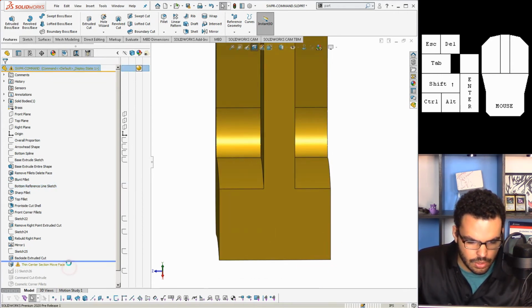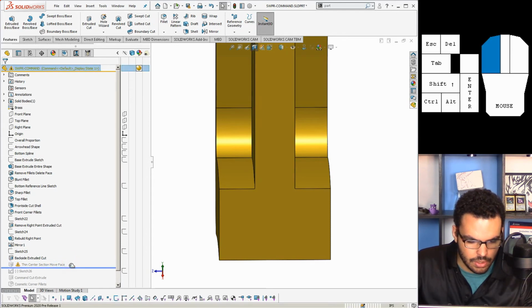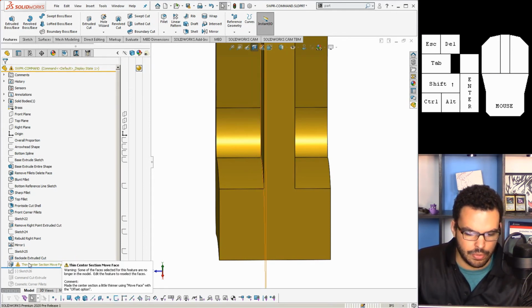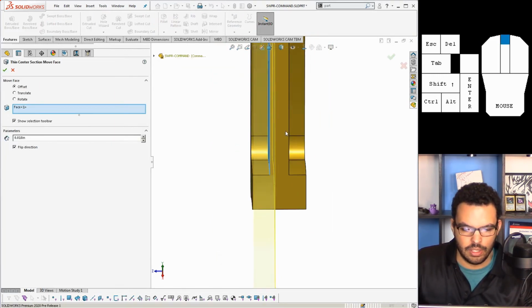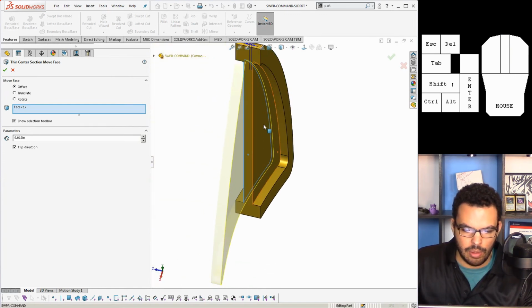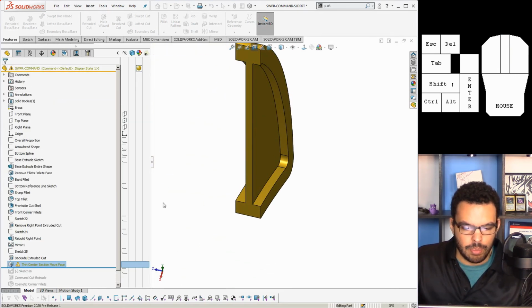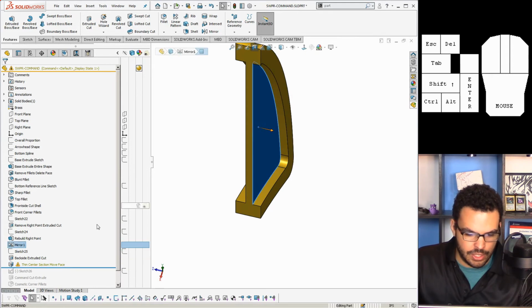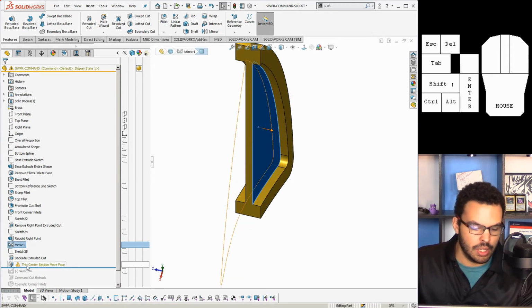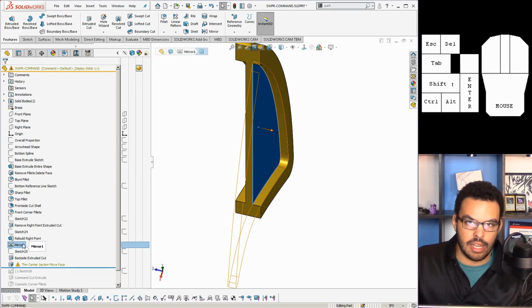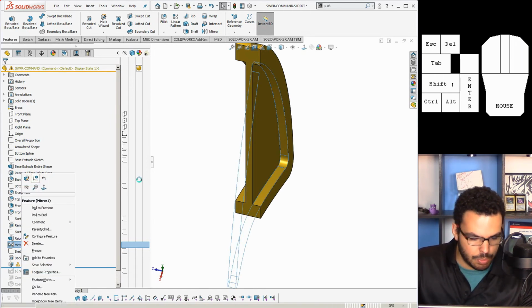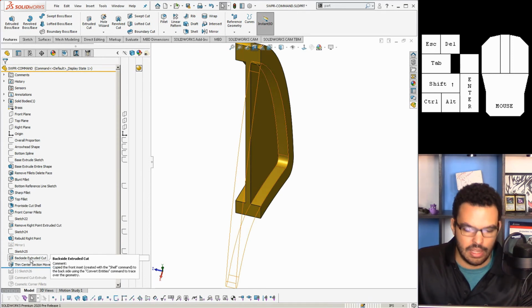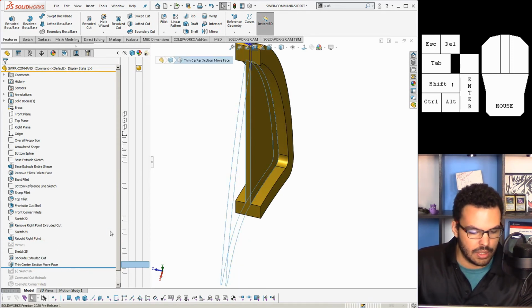So it went from here to here, and this thing is failing too. And actually, I know why, because it's missing the back face, isn't it? Yeah, I probably picked these 2 faces, but since this back face belongs to the mirror 1, this command doesn't recognize the face that belongs to this feature. So instead, I'm just going to suppress it and just leave it to the back. Yeah, there we go, the backside extrude cut.